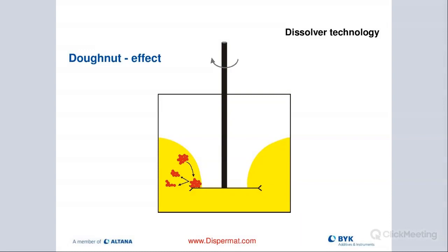Over here, you can see the breakup of the binding forces. So if I optimize my tip speed, I have the right viscosity. We're looking here between 2,000 to 5,000 centipoise. That's really optimum to get a good donut. You can also get a donut, obviously, with high viscosities, but usually for most coatings, we see really good results in that 2,000 to 5,000 centipoise viscosity range.